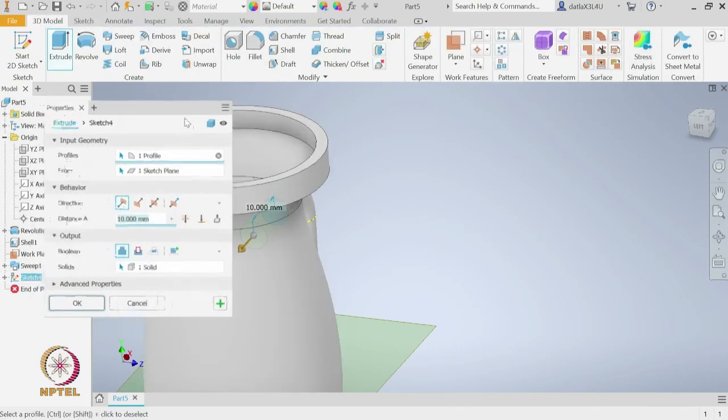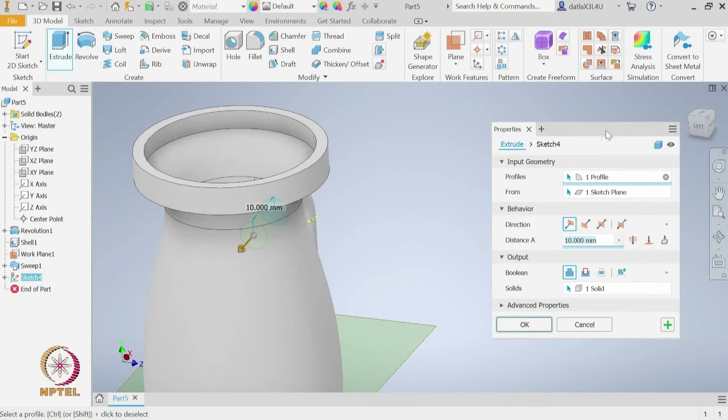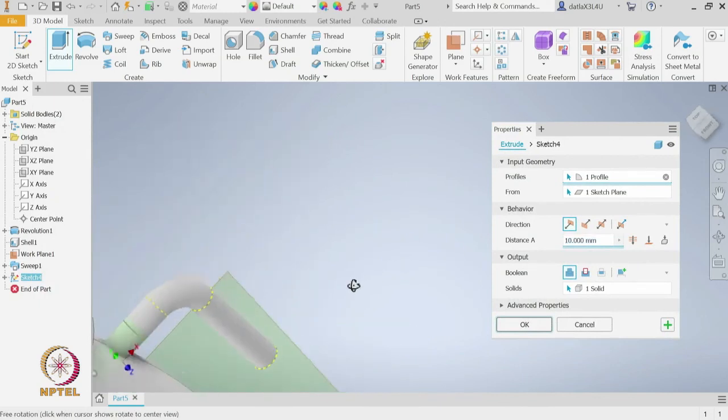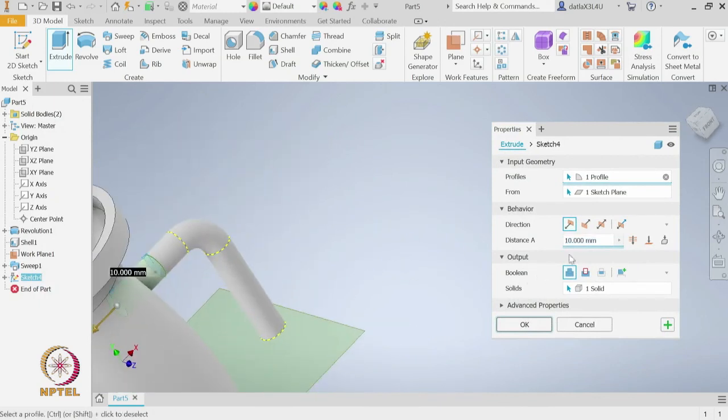Now, since we started with the extrude, it is already trying to create this extrude tool. By default it has chosen the distance, but now we can either choose through all or 2, where I can say 2 and it can go until it touches this solid of the vase, but now I will use this 2 next.